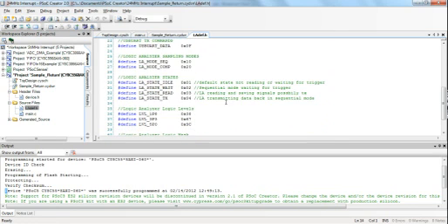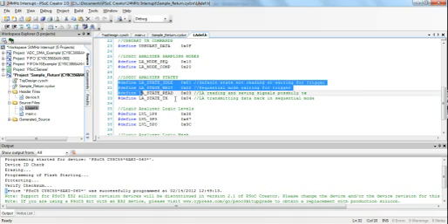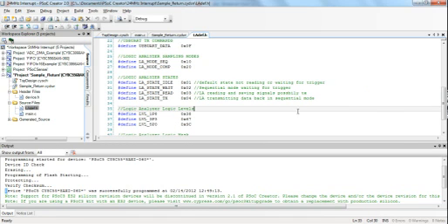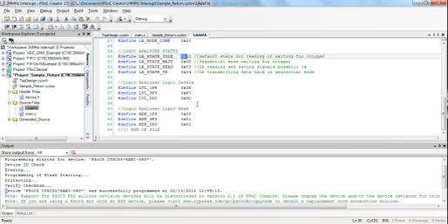Here are a couple definitions. Basically, the logic analyzer has four states: idle, wait, read, and transmit. I use idle, read, and transmit in this. Wait is for waiting for interrupts on a pin to begin sampling, but that's not implemented in this. Read just means the logic analyzer should start reading the signal. Transmit means it should be sending the signal. Idle means it's just doing nothing.